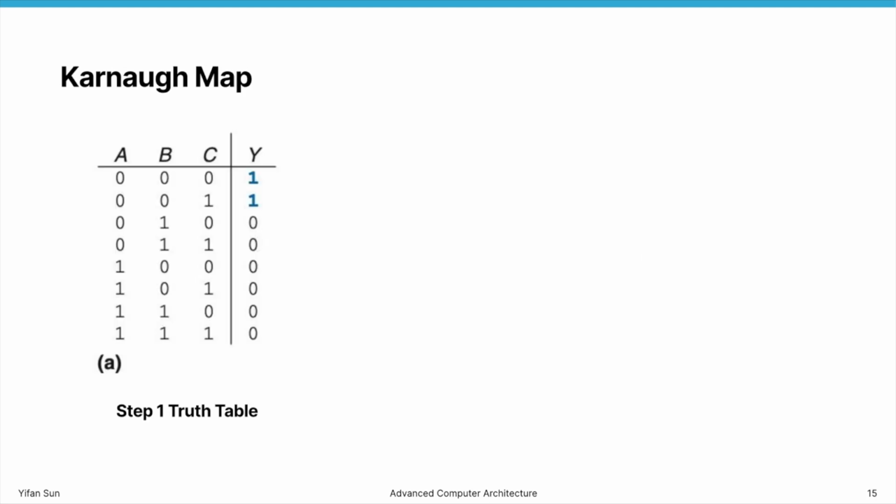Okay, write down the truth table, identify the ones, then write the product form of each one, represented with proper prime sign symbols. Then we can say, okay, it's this one.